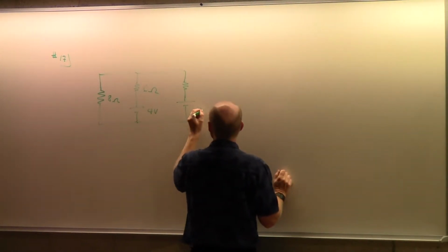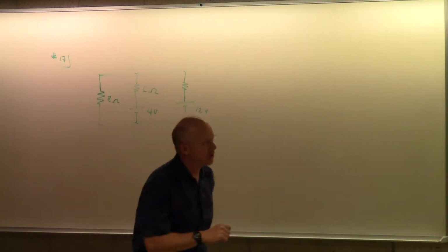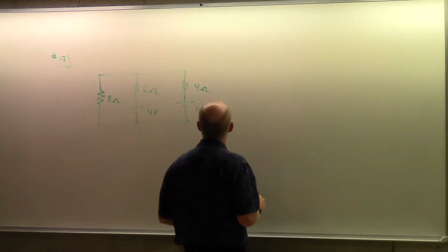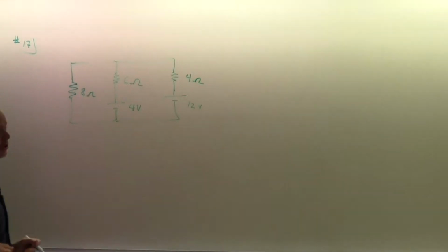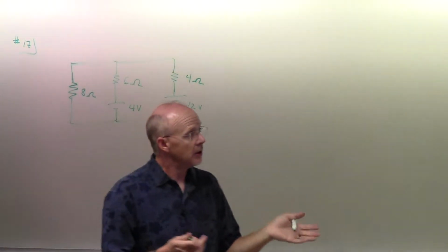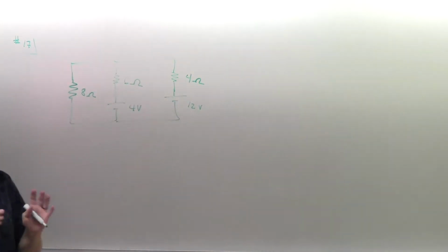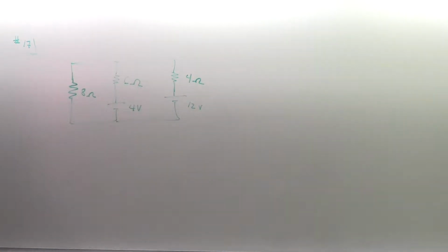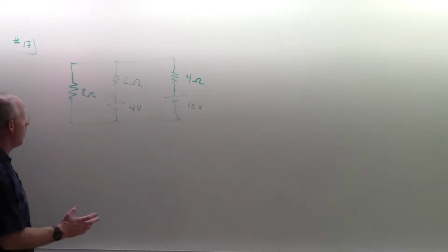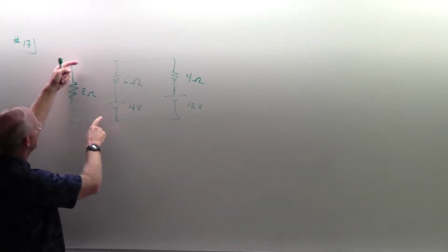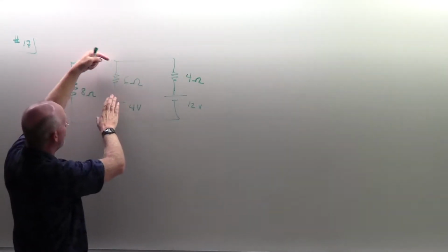And so that makes the other side of here, what was over there, a 3 and a 1, for a total of 4 ohms. So this would be the equivalent circuit of that, realizing that 2 pairs are in series. And I can make it now a little bit simpler. But this is where I would get stuck if I tried to say, are any of these in series and in parallel? And you can kind of see that no, I mean, clearly they're not in series, because to be in series, the current from this one would have to go and not have a junction. It would have to go right into that one.